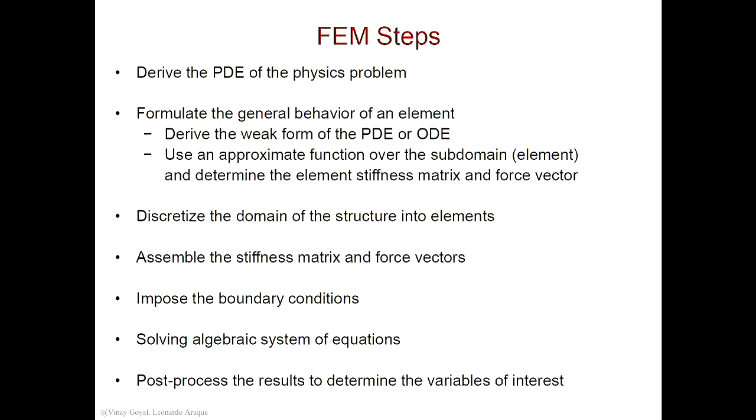Then you take the structure that you're interested in, you discretize the domain into elements, and then you assemble the stiffness matrix and force vectors. You impose the boundary conditions, the loads also, and then you solve the system of equations. And then you post-process the results. Those were the steps. And I'll keep repeating this every lecture to remind you.